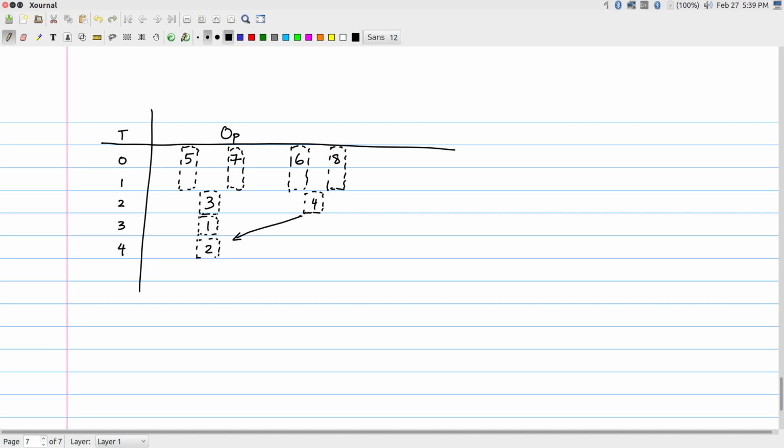Okay, so this schedule where I have 4 multiplications all scheduled at time 0, 2 additions scheduled at time 2, and one addition each scheduled at time 3 and 4 is the so-called as soon as possible schedule. From a hardware point of view, it's bad. I mean, it looks bad because I basically need 4 multipliers and 2 adders, right, in order to realize this hardware. Whereas I know that I can actually implement this using 1 multiplier and 1 adder.